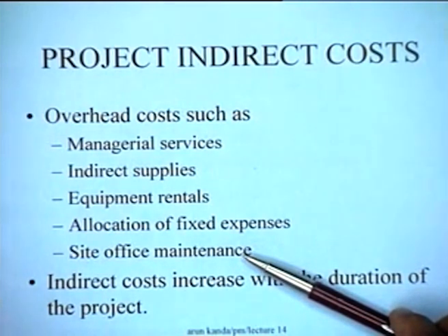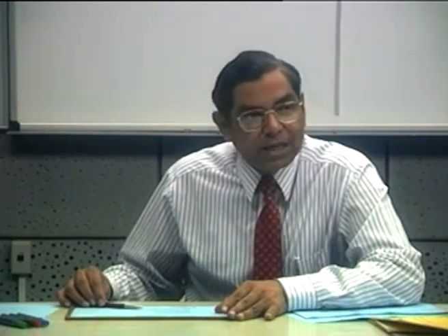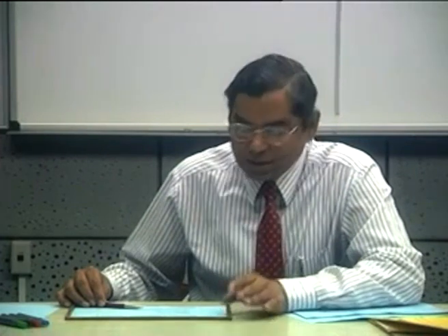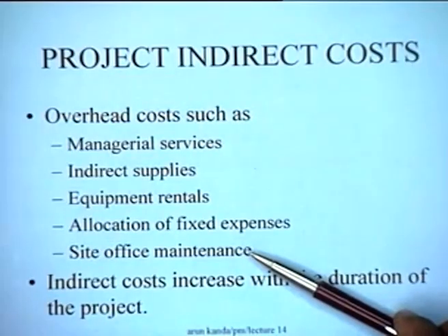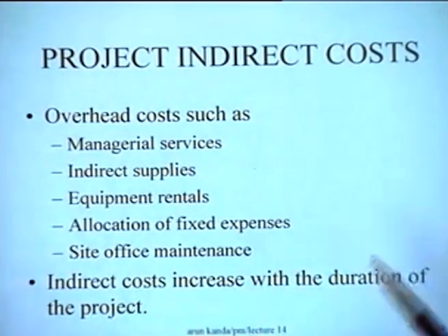As long as the project is in progress, you would have to maintain a site office, and the costs associated with that site office are dependent upon factors like how long the project is in operation, because you will have a per day cost of operating the site office, and therefore you would have these kinds of indirect costs. The important thing to note is that all the indirect costs increase with the duration of the project typically. The longer the duration of the project, the more you have to maintain the site offices, so there is a per day cost associated with that.